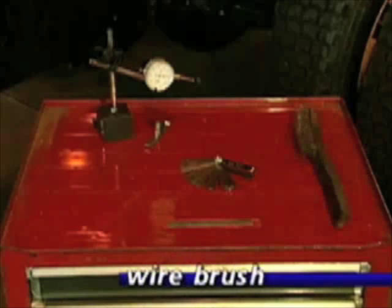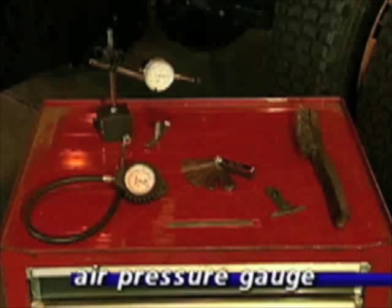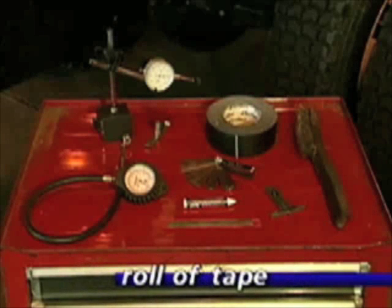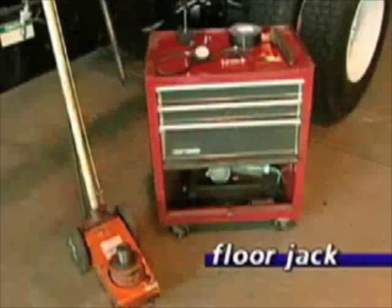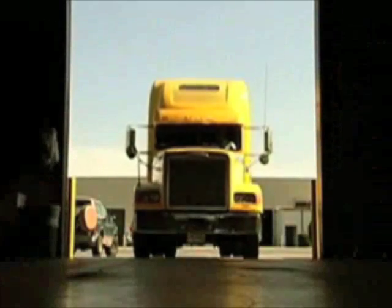A wire brush, a tire tread depth gauge, an air pressure gauge, a tire marking crayon, a roll of tape. Any tape will work. Its purpose is to smooth out a dry block tread to assist you in reading the dial indicator. A floor jack and a T45 tire iron or long bar to lift and position the tire wheel assembly. We are now ready to begin.